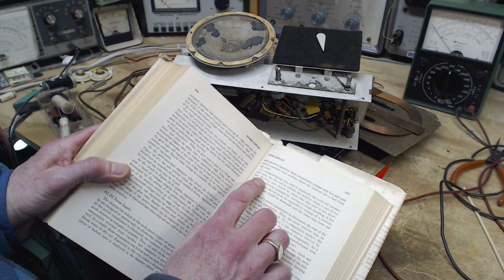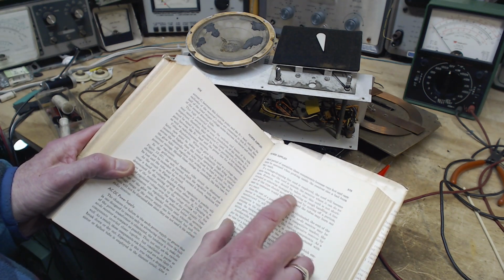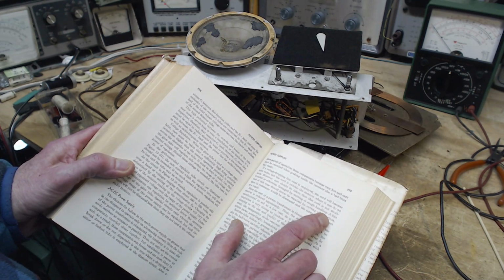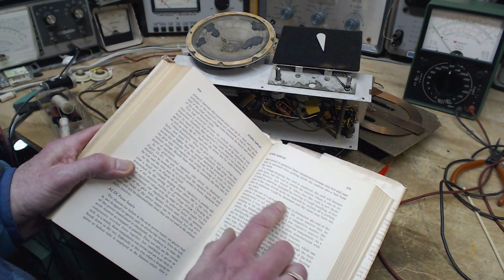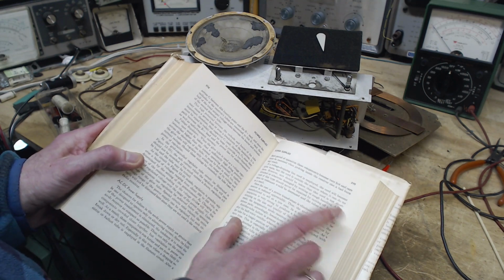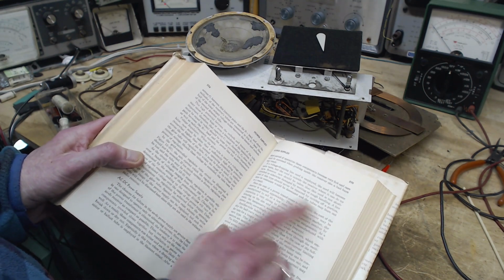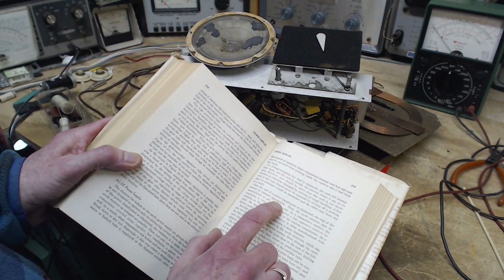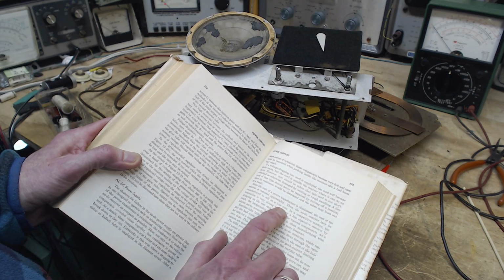Oh yeah? However, care should be taken that this cord is not short-circuited or otherwise damaged by wetting or rough handling. A line cord of this type should never be repaired by cutting off a portion, since its resistance would be decreased and the tubes may burn out as a result. Since the cost of a power transformer is eliminated, the cost of the receiver is reduced appreciably. Thus, the AC/DC receiver may be manufactured to sell at a low cost.